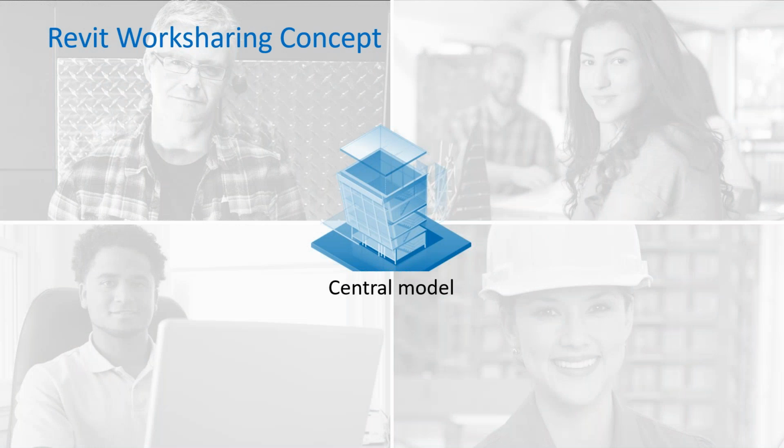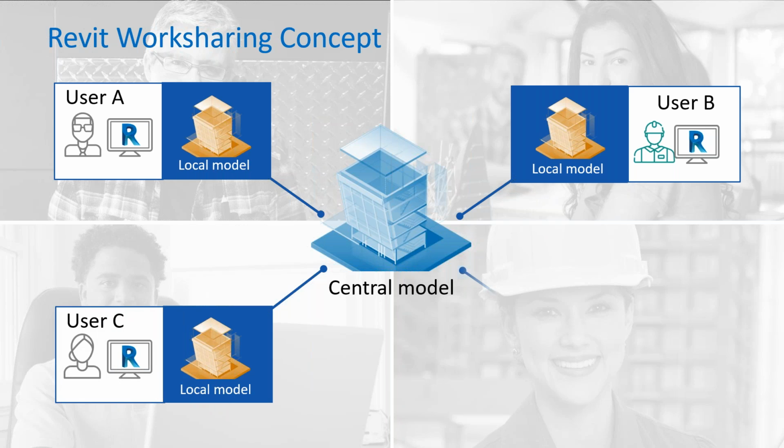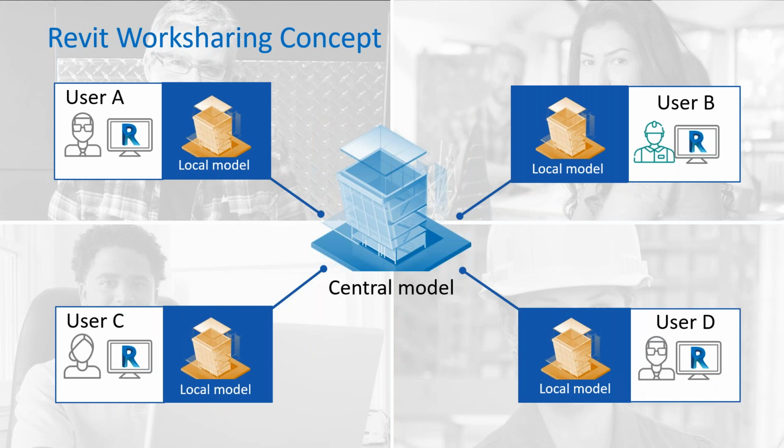Okay, so first as a review, BIM 360 design is very much based on the Revit work sharing concept, as I mentioned last week in the session. It essentially means that the whole concept of having local users and local models and connecting to a central model hasn't changed. I think that's one of the greatest benefits of BIM 360 design: all of those users are up and running in a matter of minutes. I tend to say it's as if you were to move your central file, your central model, into the cloud, because that's really what BIM 360 is all about, connected BIM, BIM with the power of the cloud. So we're just pushing this central model into the cloud.